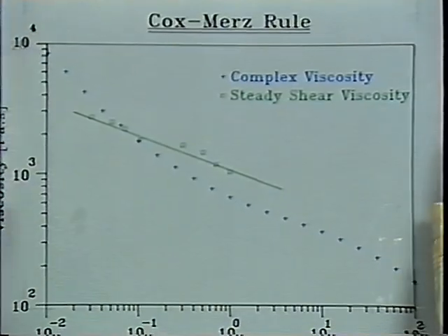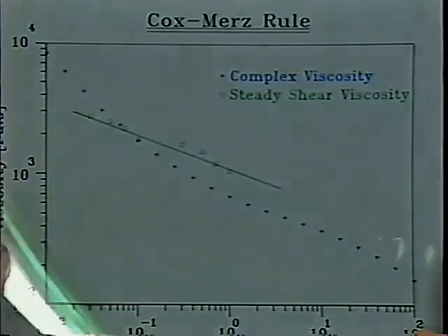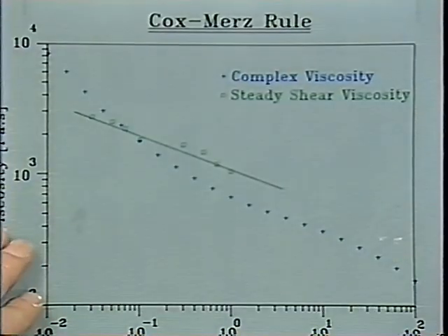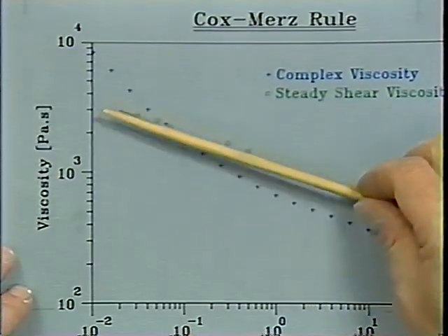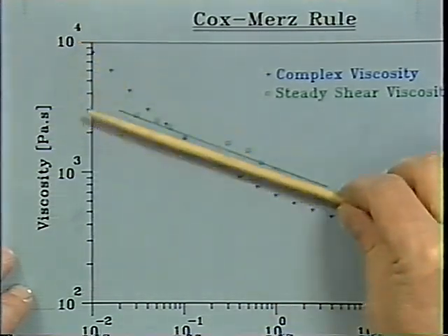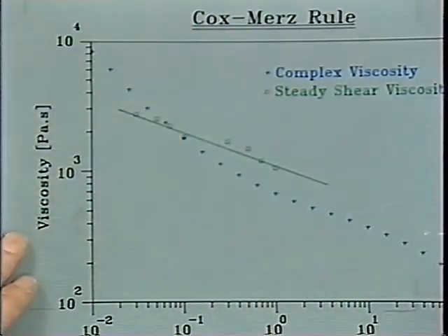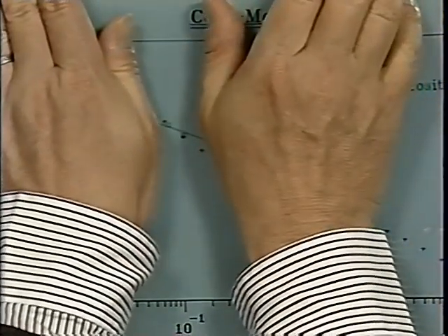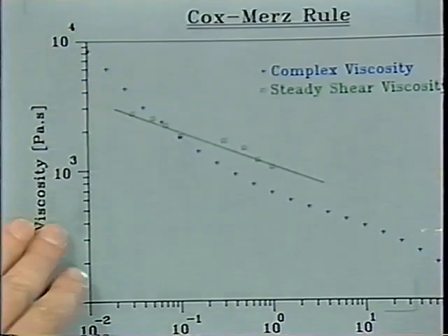Conventional polymer melts are also modeled by the so-called Cox-Merz relation, where the dynamic viscosity is reproducing the steady shear viscosity. It doesn't hold for liquid crystal polymers, which is well known. The steady shear viscosity is in the vicinity of the dynamic viscosity, but it has a different slope. So somewhat, if you would operate out here, you would say there's no agreement at all. It's always easy to take the crossover point and say there's agreement. It's really a different structure in those two different curves.